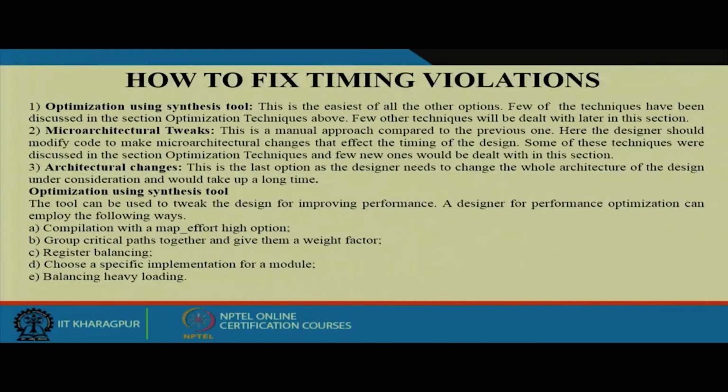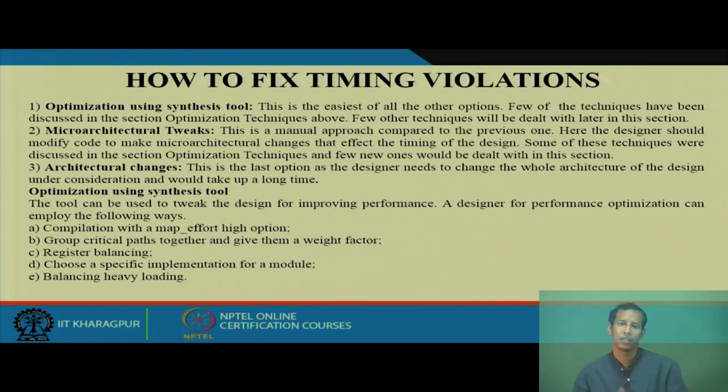In timing analysis we can get two types of timing violations: the setup time violation and the hold time violation. Now the question is, if I get a violation, how do I fix it? One technique is to optimize using the synthesis tool.